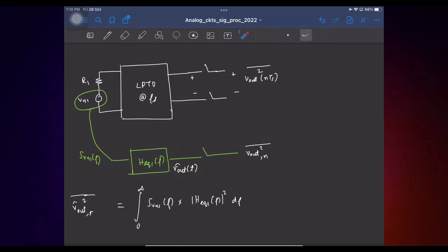So why do you think it is the same? Because it is stationary, and the samples will follow the same kind of pattern. Simple logic: this is a stationary random process passing through an LTI filter. The output is also stationary, so the statistical properties are going to be the same when you observe it at any time instant. You take it at 0, Ts, 2Ts, or at whatever time instant, the properties are going to be the same.